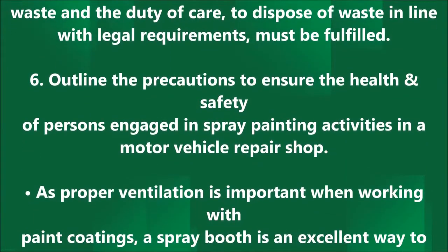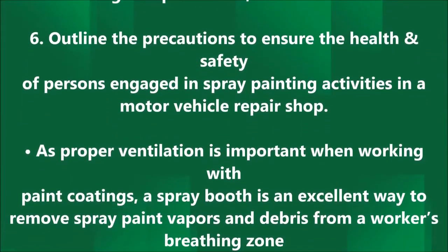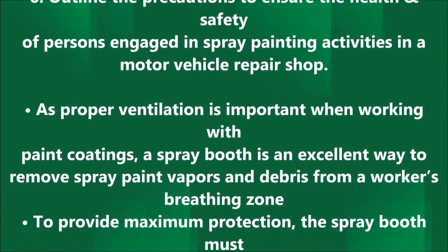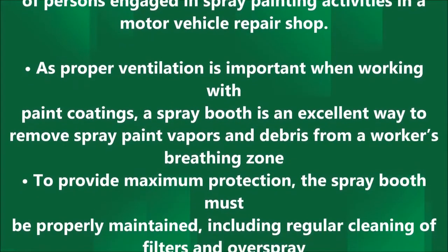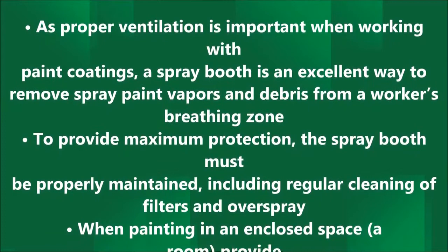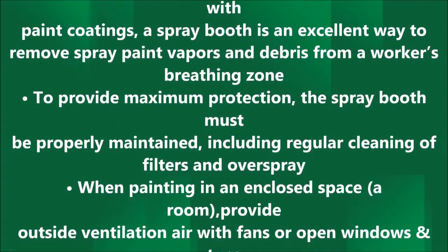6. Outline the precautions to ensure the health and safety of persons engaged in spray painting activities in a motor vehicle repair shop. As proper ventilation is important when working with paint coatings, a spray booth is an excellent way to remove spray paint vapors and debris from a worker's breathing zone. To provide maximum protection, the spray booth must be properly maintained, including regular cleaning of filters and overspray.